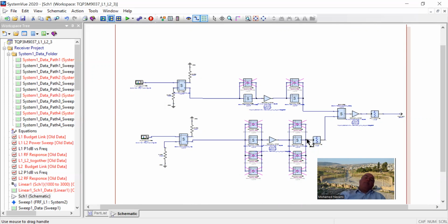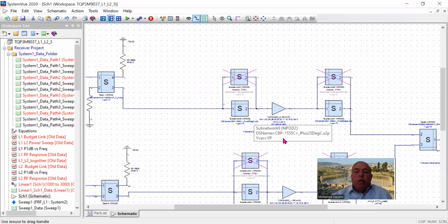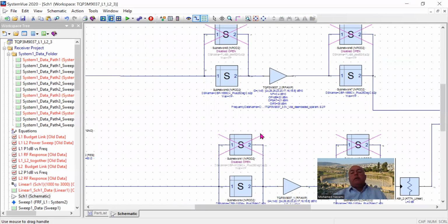post-layout EM verification of the system, because we have to put in all the passives for the amplifier and for the filters. We might have to include some interstage matching, because we have to put this in ADS now and start looking at the overall slope, gain variations, and noise figure.